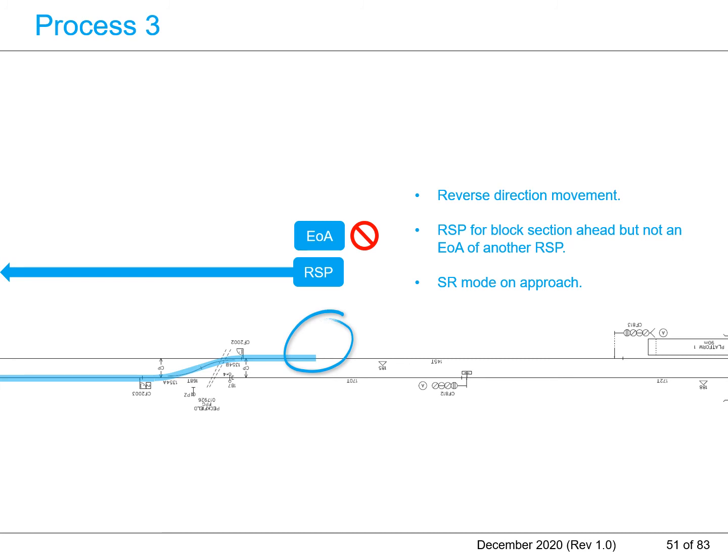perspective. When the onboard ETCS does not have movement authority beyond the RSP, the EOA is the front end of the train, after changing the active cab end, for the turning back operation. The train without the movement authority from the radio block center can move closer to the RSP in SR mode,